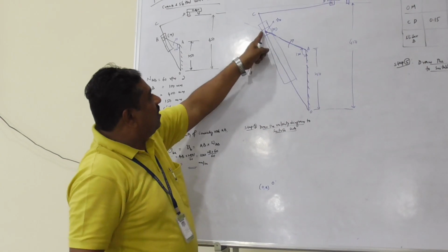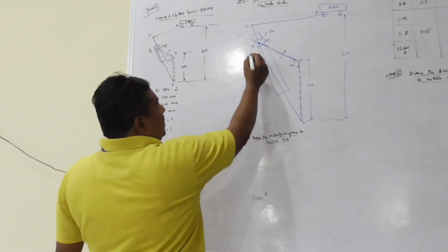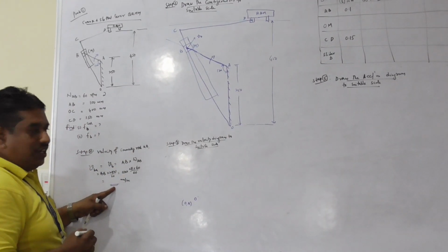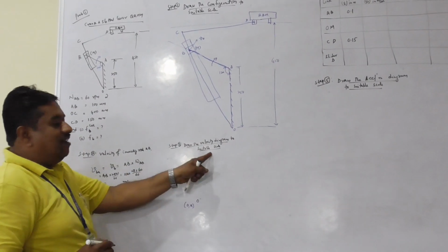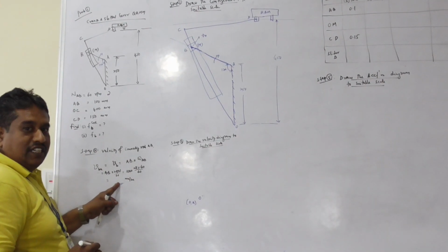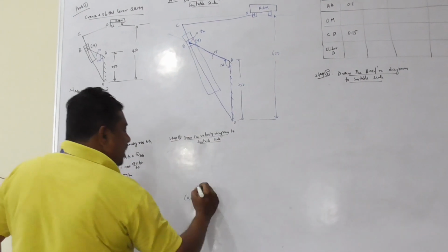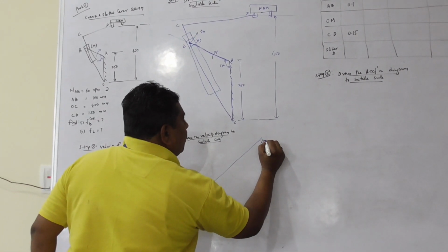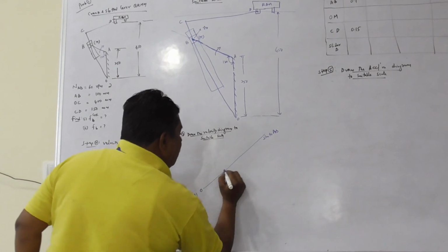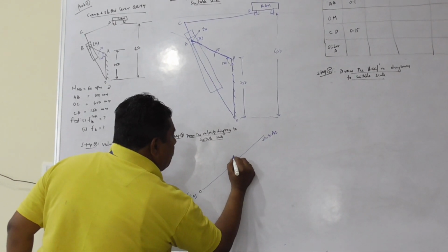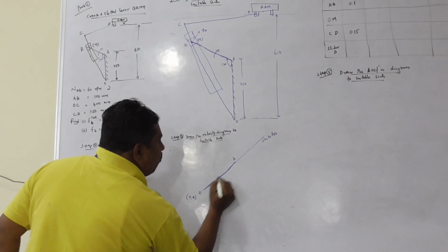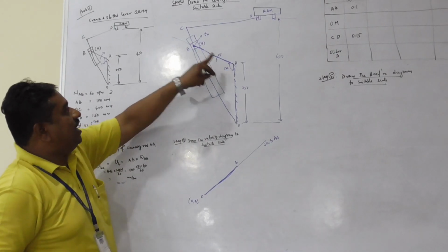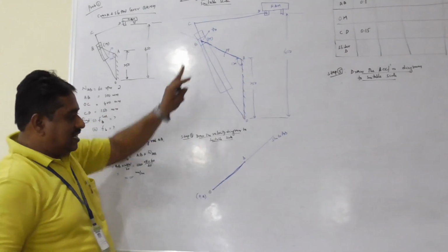Now consider the connecting rod AB. Velocity of B relative to A is perpendicular. Therefore, the magnitude is known. With respect to the scale of the velocity diagram, for this magnitude value, in a direction perpendicular to AB, draw a line and fix the point B. Vector OB represents the velocity image of the connecting rod AB of the quick return motion mechanism.